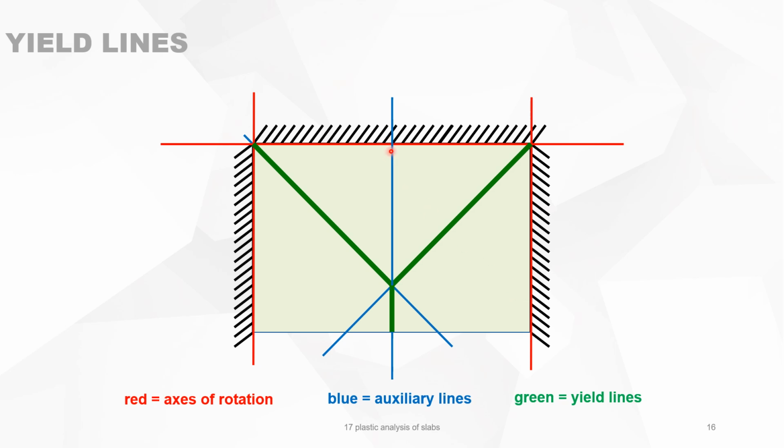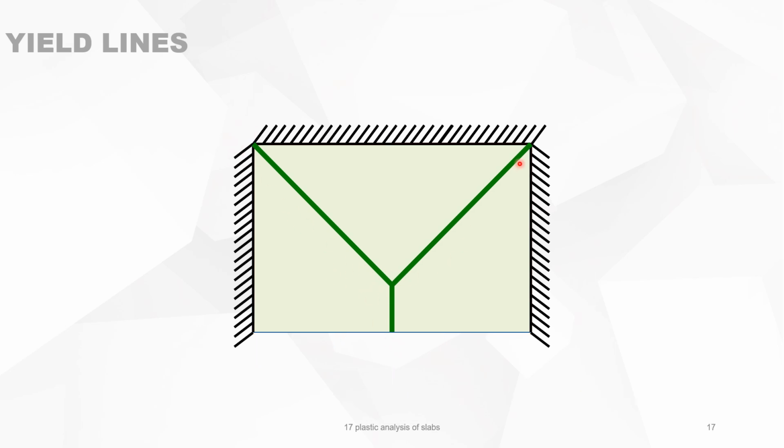Making this a yield line is not possible because if you do that, you do not have a mechanism. That's why the last rule, remember, of yield lines, you always need a mechanism so that the different subregions can rotate. Okay, so this is now the yield lines for this type of slab.